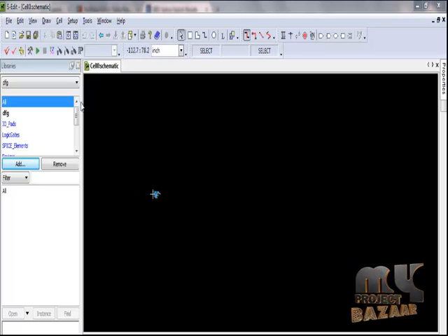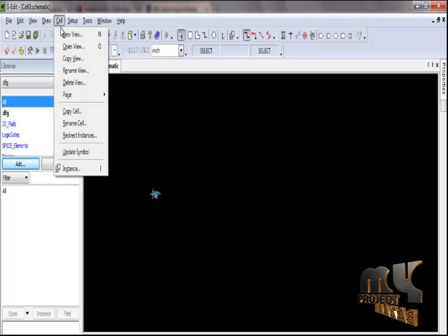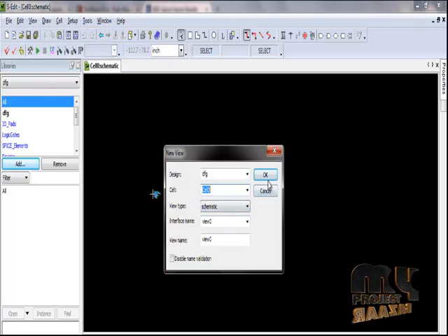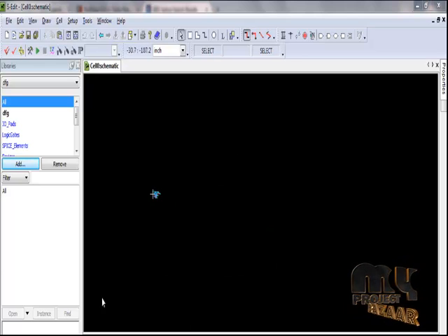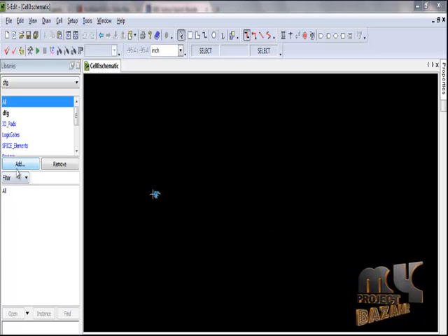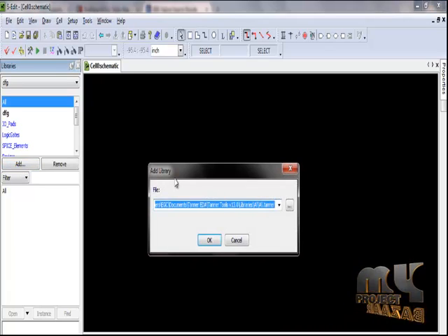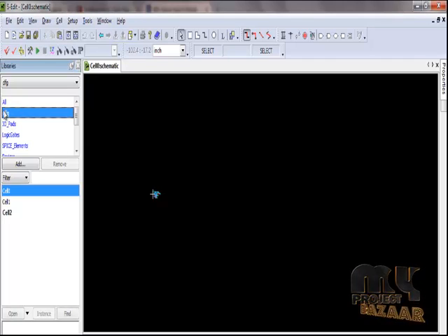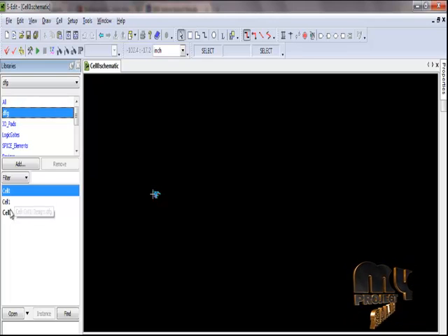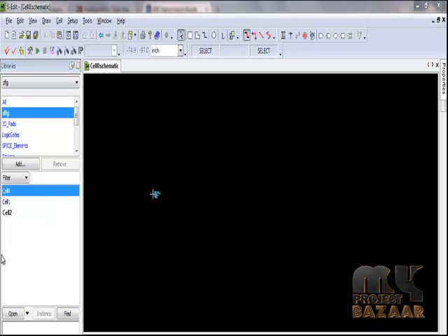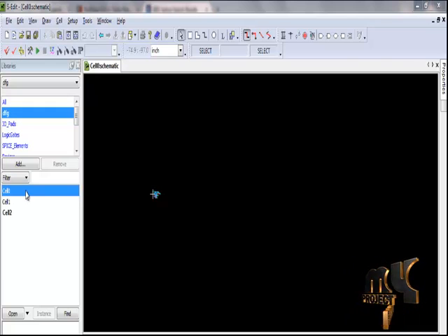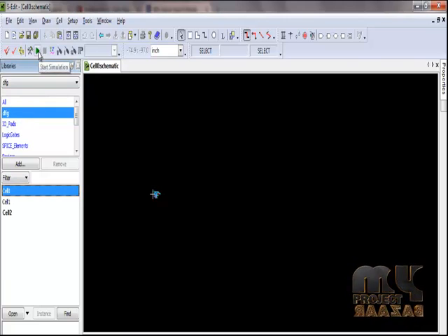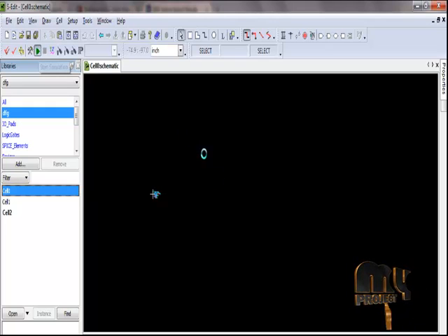After creating a file, create a new cell from the Cell option, New view, Create a cell. Click OK to create a new cell. After creating the cell, select the Add option to add the library files from this banner. Select a file name to view our different cells. We implement this design using three different cells: cell 0, cell 1, cell 2. Now we simulate the first cell. Select cell 0, the Run option, Start simulation.